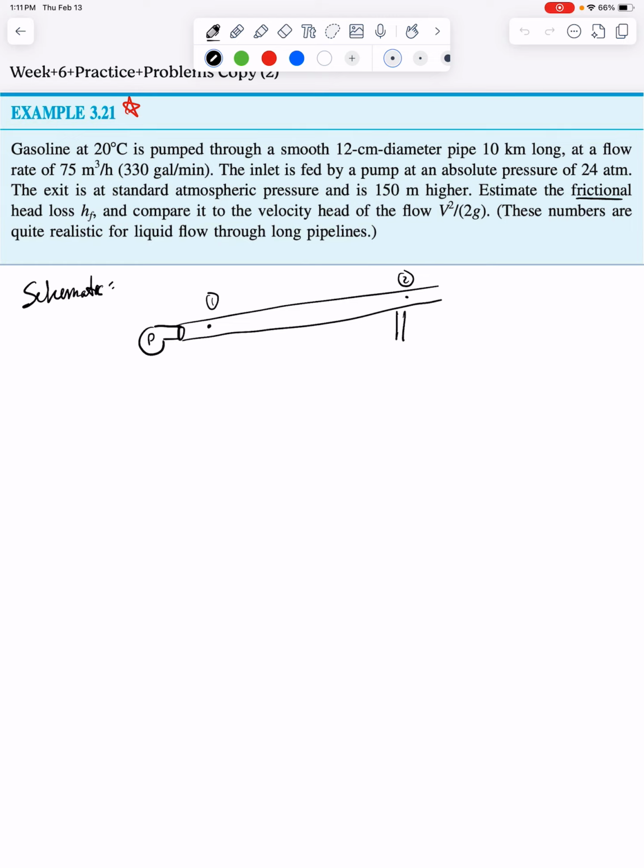So I guess to quickly go back and recapitulate what's going on, we have Bernoulli's equation, which we've been working with last week. And Bernoulli's equation essentially says that the three energy terms, internal energy, kinetic energy, and potential energy, combine to be our total energy value. And as long as we're on the same streamline with some other assumptions, such as steady state, incompressible, inviscid, this total energy value, the sum of those three terms, will not change.